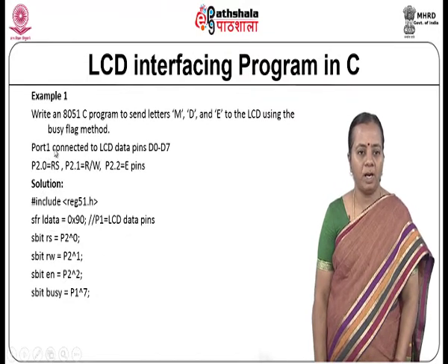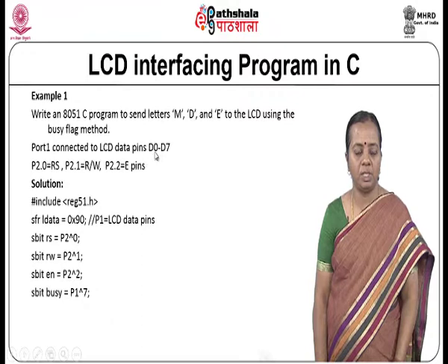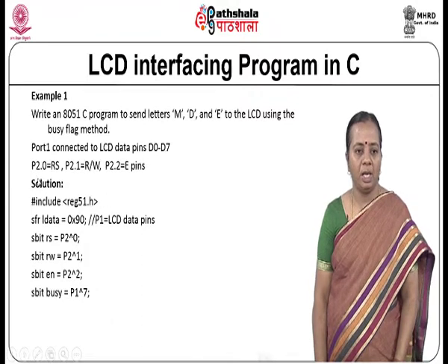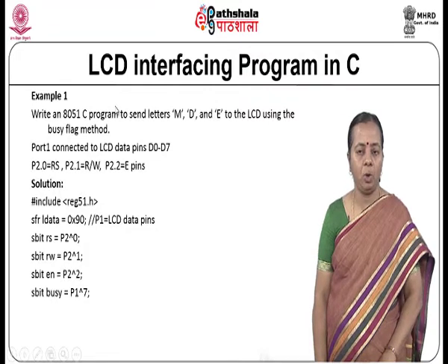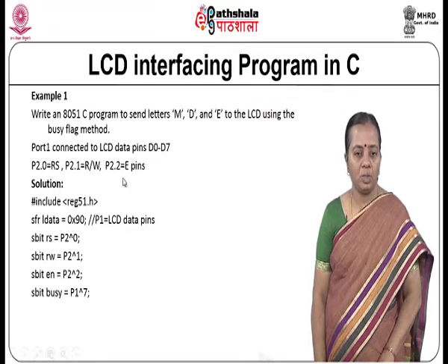Here, port 1 is connected to LCD pins D0 to D7. Whenever you write code, you need to identify where the LCD data pins are connected.